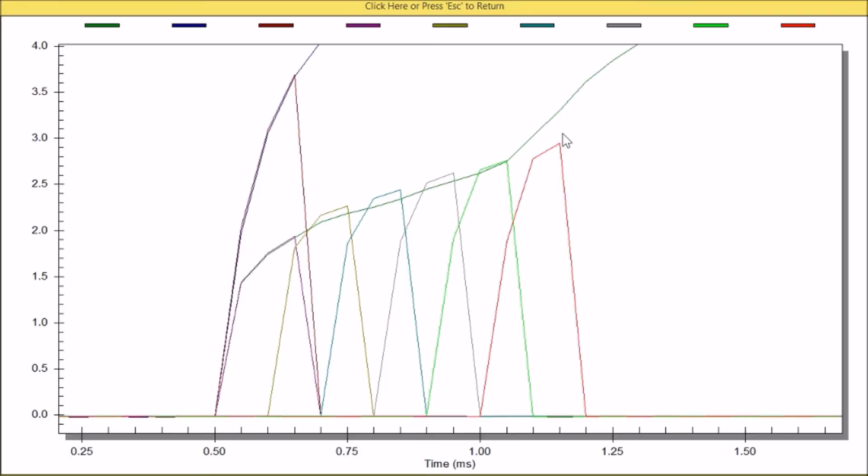Here's my shelf reproduced. Now notice that once I pass the shelf, I begin to fall off the track. The reason for this is because the pulse width is narrow and is taking time to get all the way up. In this case, we already used a 2 millisecond test to get the capacitor totally saturated. Here it is traversing a different path because the pulse width is starting to slow down how much of the remaining polarization can be switched in pulses. So it's a nonlinear device. You change how it's stimulated, and you get a different result. That's also affected by its memory state and its history.